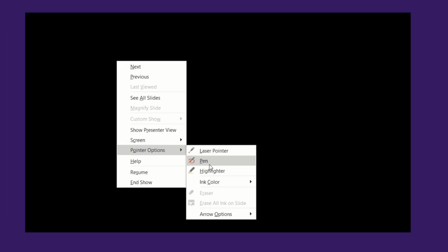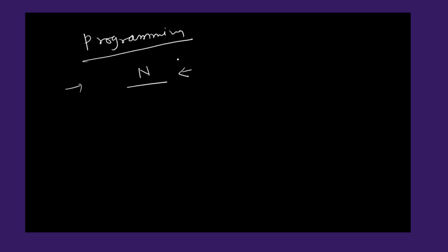Okay, now let's understand the programming part. So we have to do some basic configuration like selecting the prescaler. So we have to set the prescaler value, and this prescaler value is set from the register which is called TCCR0, the timer counter control register, TCCR0.